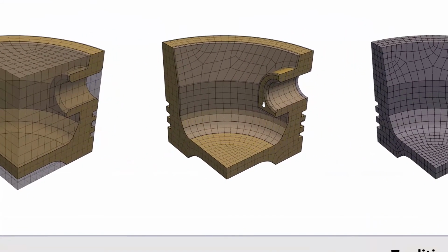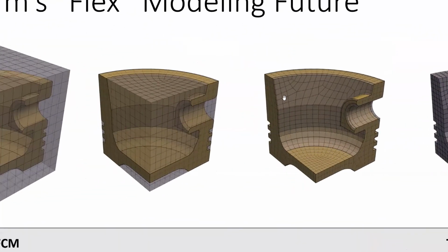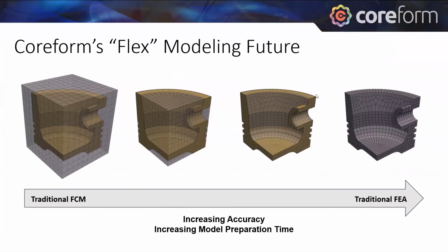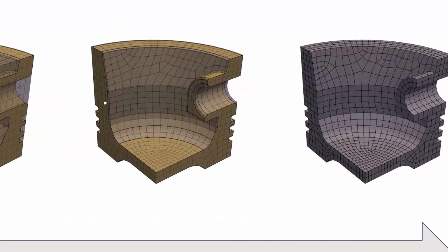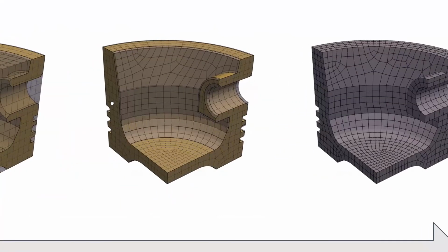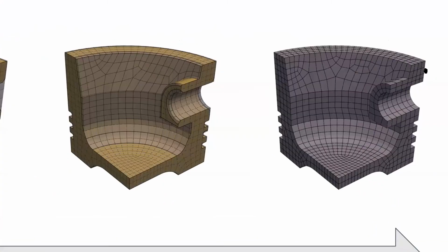And so that's the whole spectrum. What has been said earlier is that if you're using these immersed methods, or whatever you're calling them, you can increase the polynomial degree or something like that and capture those complexities. Whereas if you go to the far right and you've removed them, you can no longer capture those no matter how much you refine the mesh. Right. You've removed them from the geometry.